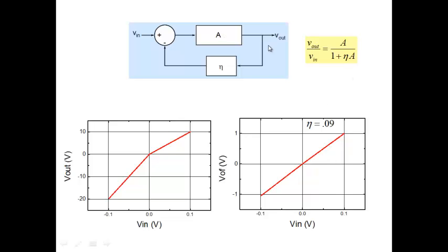But then how is the distortion absent? How am I getting a pure sinusoid? Because the input to the amplifier A is a distorted sinusoid, and the distortion is opposite to what my amplifier A will do. That's how the two things cancel. So if you go inside and find out what is really happening in terms of signals, the conclusion is that if the output is a pure sinusoid, then the signal here has to be a distorted sinusoid, with distortion opposite to what A will do.